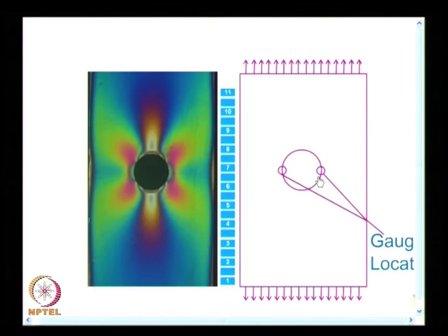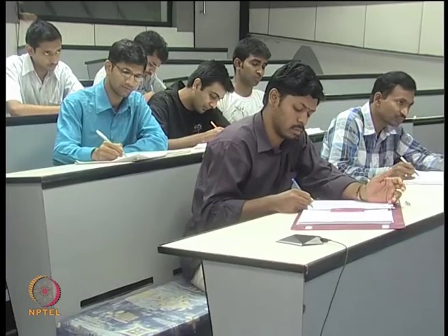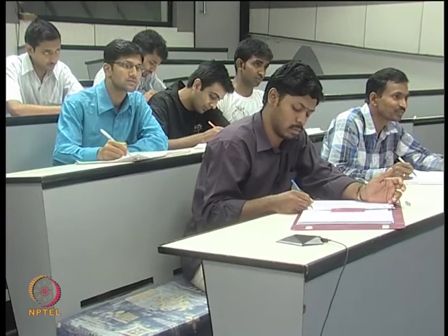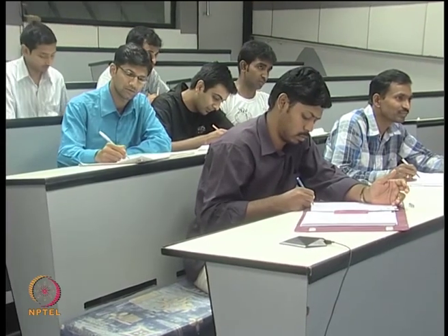All these are difficult propositions. If the hole is very small, what will you do? So, you appreciate how difficult a point by point technique is to apply in stress concentration zones. I had also mentioned that the rudder of Concorde was failing, and they used a strain gauge. They found that the strain gauge was measuring strains lower than the actual, and a photoelastic coating test revealed that maximum strain was at a slight distance away, and they corrected it.